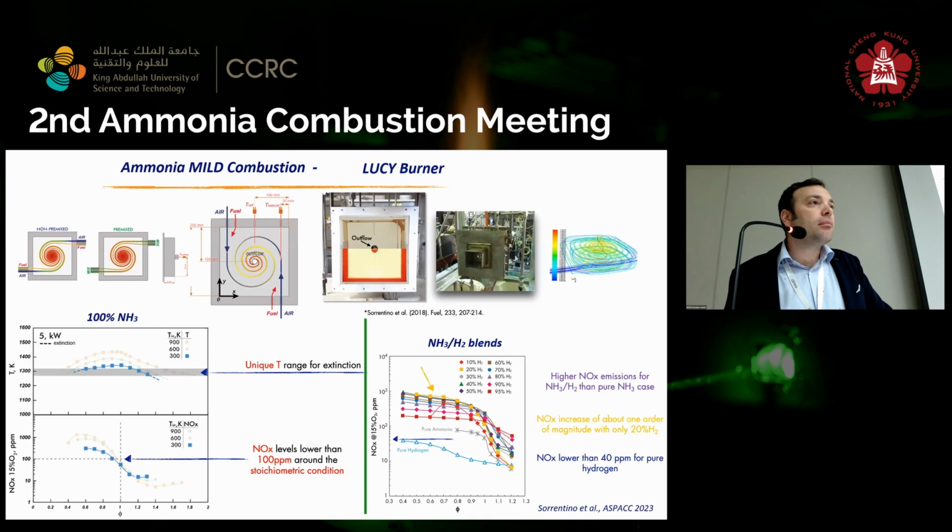The trend seemed to be consistent with the early results of Kobayashi's group and so on, where you get that minimum NOx around 1.1 or so. Where is the sweet spot there? Do you have the complementary results for the ammonia emissions as well, to see if you're landing in the same place? You mean for this case, for pure ammonia? The ammonia slip, you mean? Yes. Yeah, we have it.